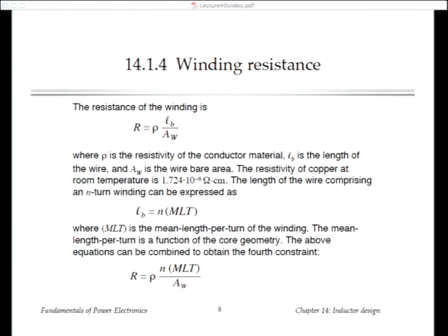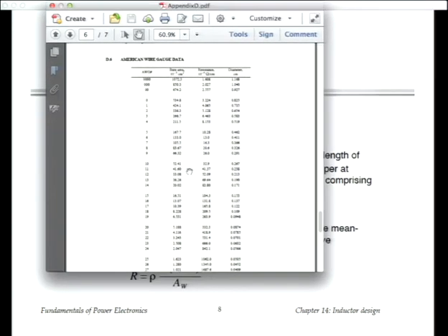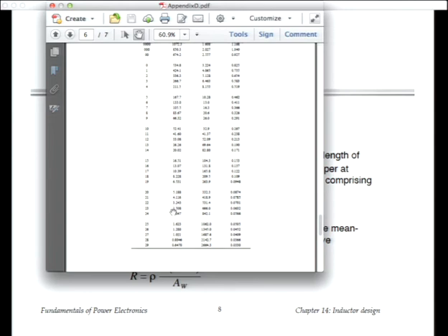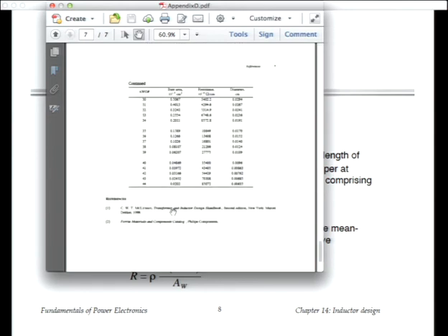Okay, just one last thing about that. Number 10 to 14 gauge wire is fat wire that's like what's used to wire houses. So, you know, here we're talking wires that can handle between 15 and 30 amps of current for that size wire. 20 to 24 gauge is what we often use for hookup wire in the lab. So it's maybe what you think of as more normal wire. And when you get into the 30s and 40s, we're getting the small wire. Wires in the 40 gauge area are like hairs in thickness. They're very thin.